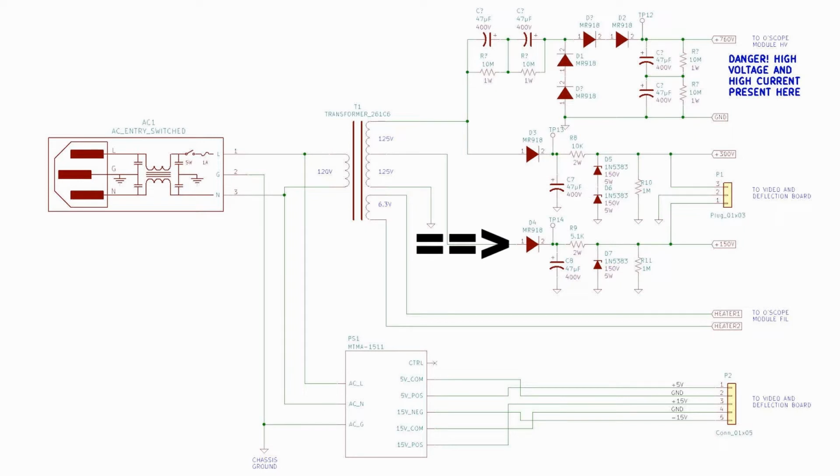Moving down to the third rectifier, we are running this one on the alleged 125 volt tap, which is more like 135 volts as I mentioned, and we're getting about 190 volts rectified on the 47 microfarad capacitor.